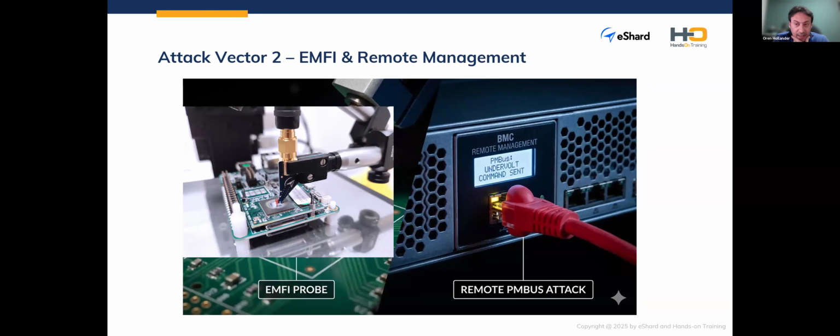The second thing that we see is that we know that electromagnetic fault injection, EMFI, uses a small copper coil to induce localized electrical current inside the silicon without touching it. So it's a non-invasive technique. This is like a ninja attack because it bypasses the physical shields that only detect contact or light.